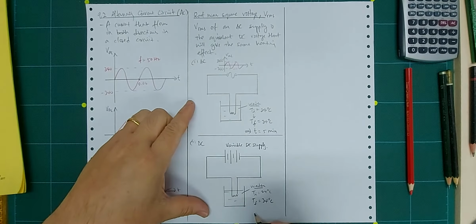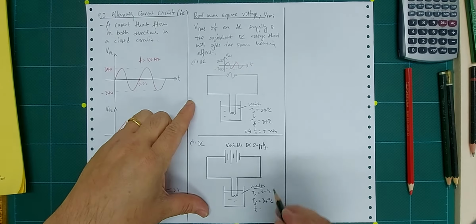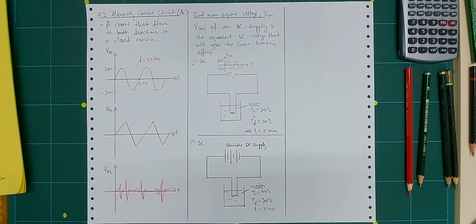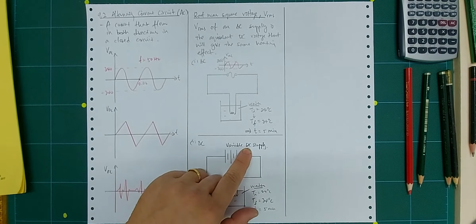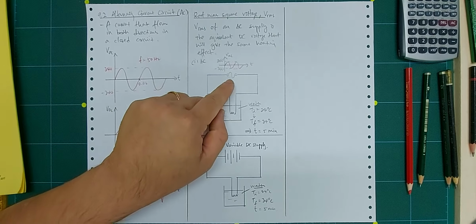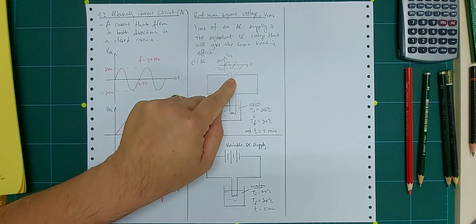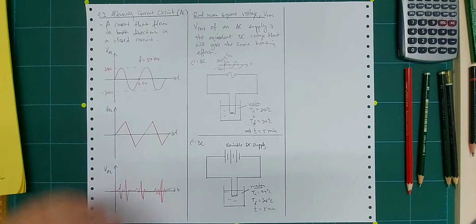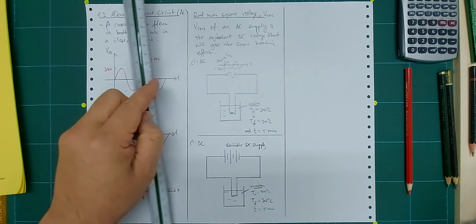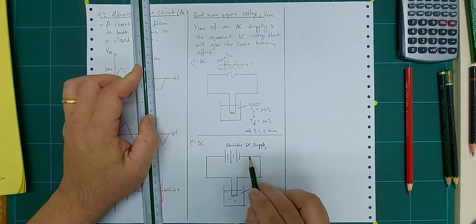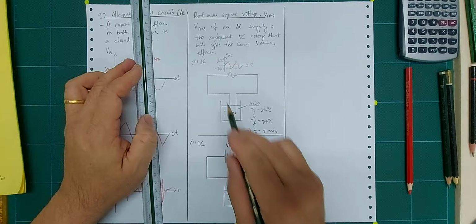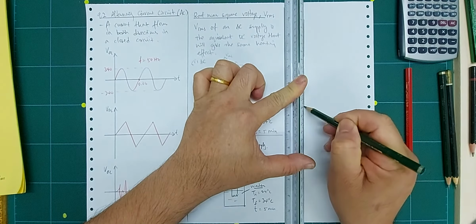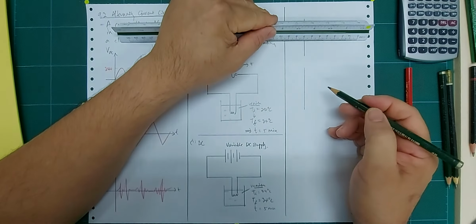If we want it to reach the temperature in the same amount of time, then we know that this DC power supply must supply the same amount of energy as the one supplied by our AC here. So how do you do that? First you look at it by comparison. The question is, what voltage do you need? Is it 340? Then we compare the graphs by looking at who has a larger surface area.